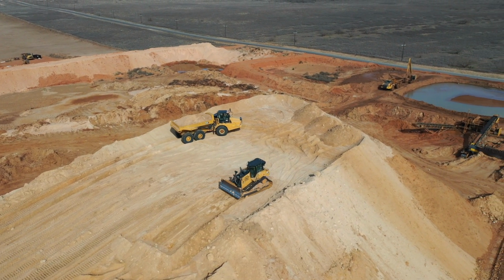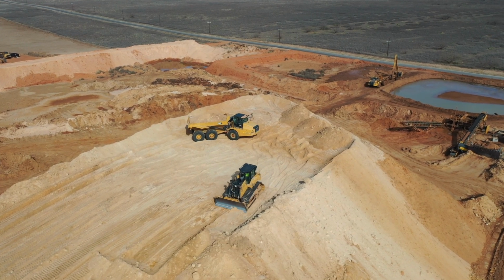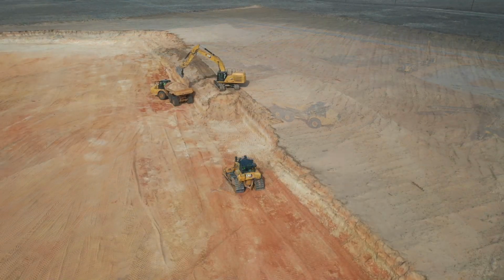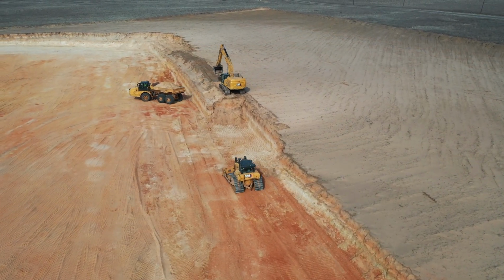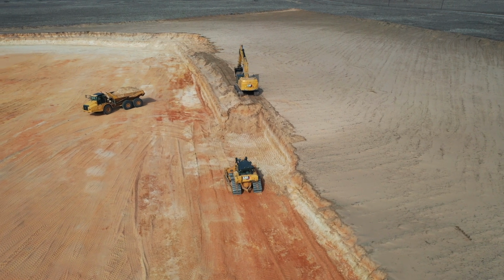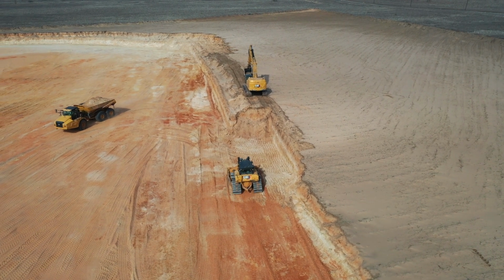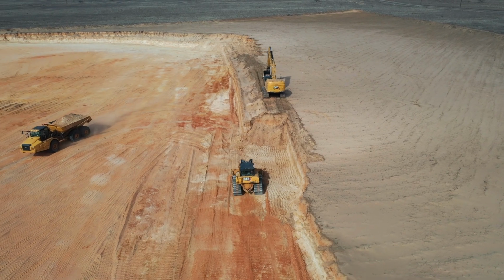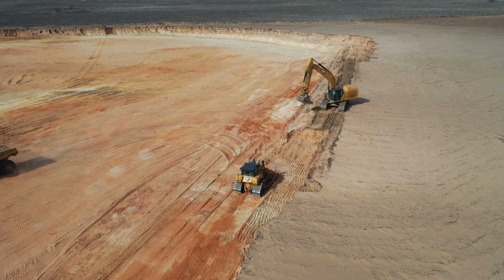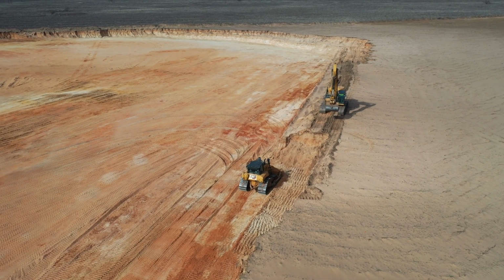Should the dozer start slipping sideways on a grade, turn it immediately in the direction of the downgrade and lower the blade. High wall positioning. When dozing toward a high wall edge, constantly examine the ground surface for development of cracks or fissures indicating separation. Push perpendicular to the high wall face, and always keep a full blade in front of you. Maintain a safe distance from the edge of the high wall.